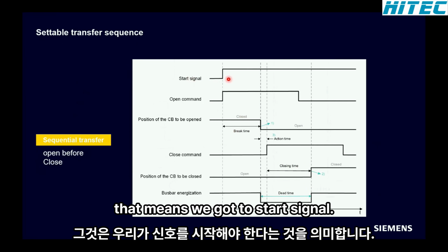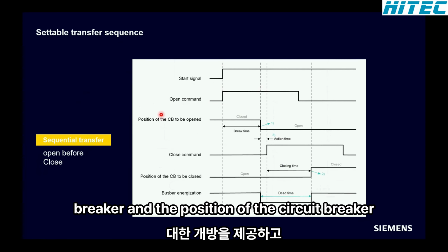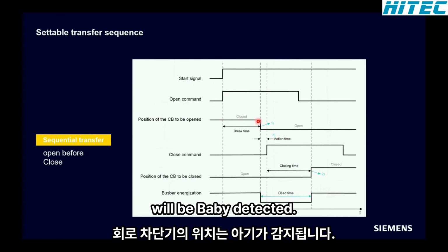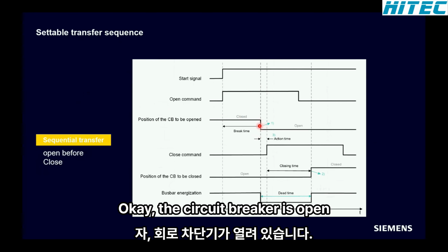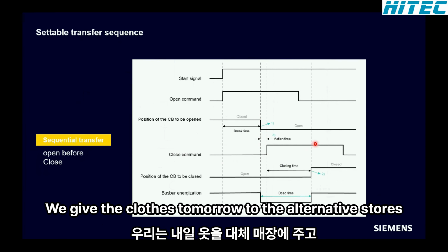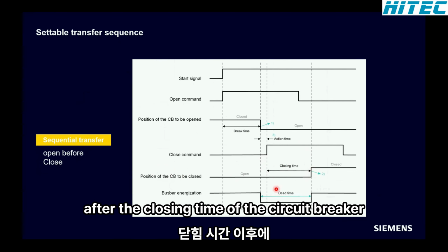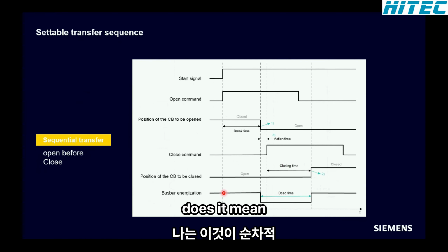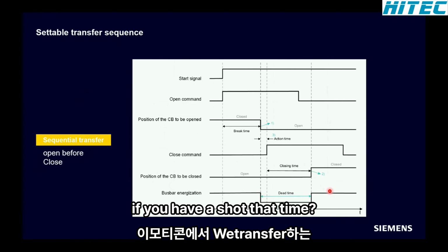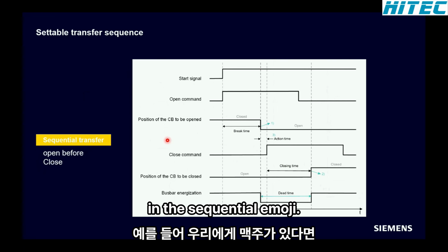That means we got a start signal. The HSBT is giving the open command to the circuit breaker, and the position of the circuit breaker will be detected. Okay, the circuit breaker is open, and then after a short action time, we give the close command to the alternative source, and the position will be reached after the closing time of the circuit breaker. For the busbar voltage, does it mean that we have a short dead time? So this is the usual way how we transfer in a sequential mode.